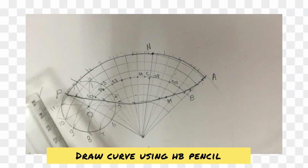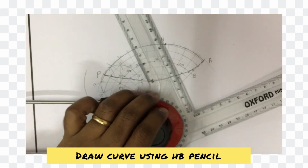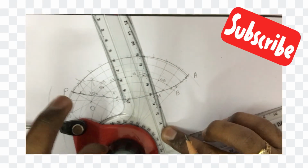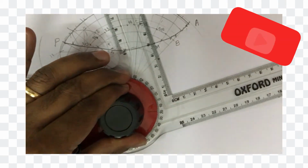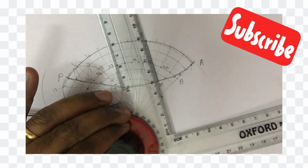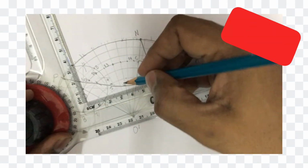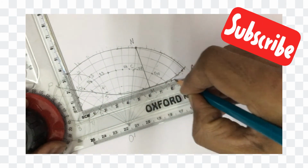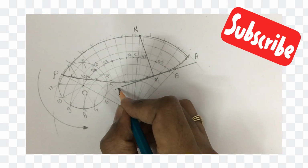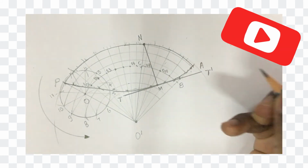Getting there, students. Later, using HB pencil, draw a line from N to M. Draw a line from N to M, fixing your drafter. Wait, because this is the perpendicular where we are going to trace the tangent. So NM is the normal to the curve, and this scale, if you take it on to the M, that is the tangent to the curve. So this is T and this is T dash. I hope you are getting my points.